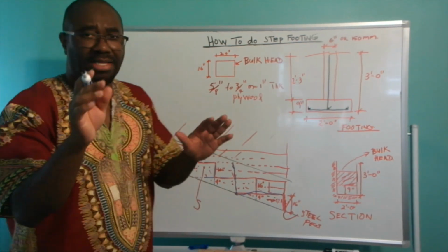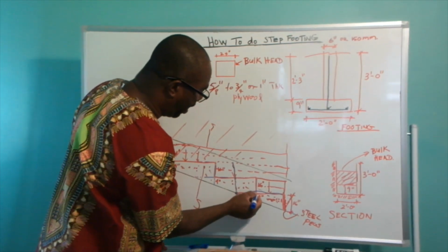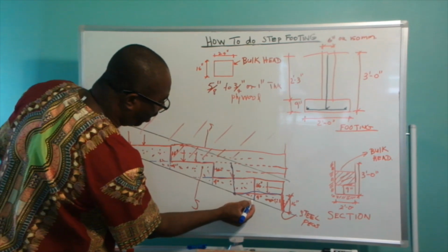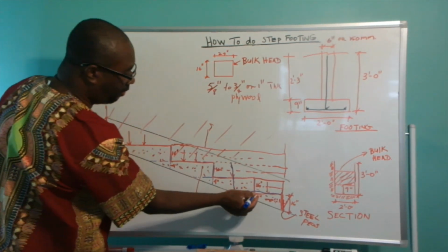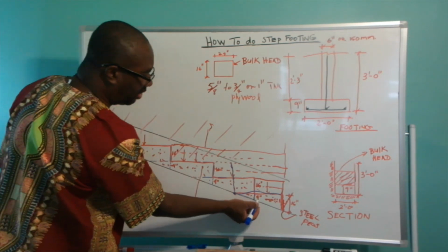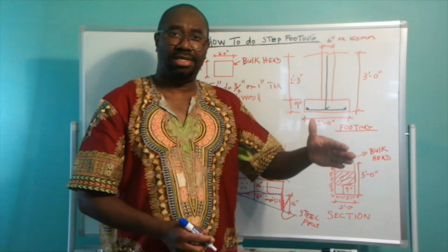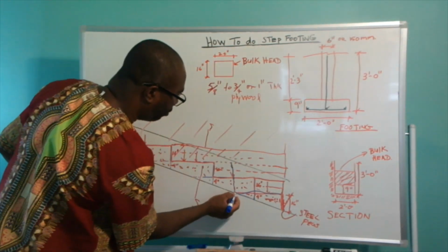And I'm saying that is not correct, because at the 9 inches point here, as you start to go up the hill towards this point, you're going to reduce the thickness of your concrete to less than 9 inches. So you're going to move from 9 inches to 8 inches to 7 inches to 6 inches until you get to this point of 0.